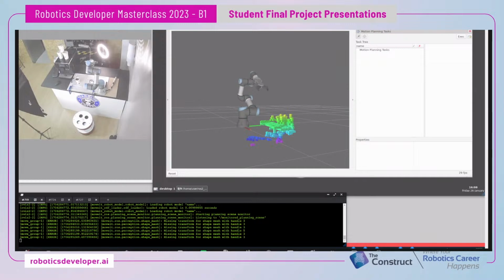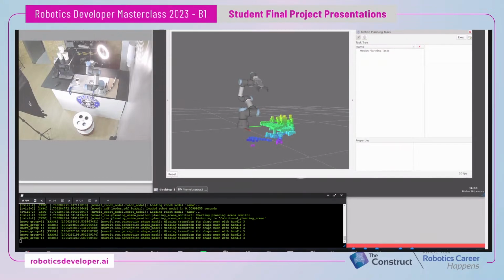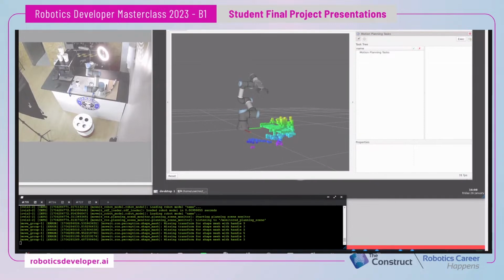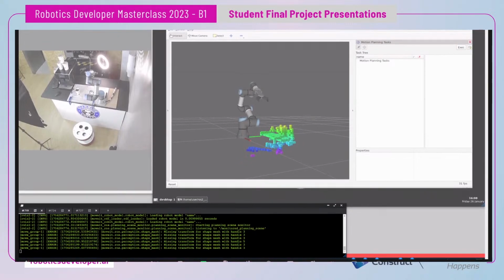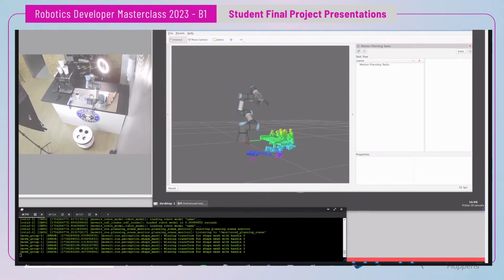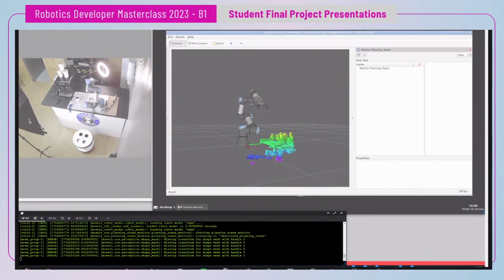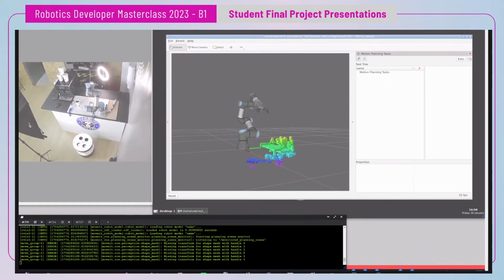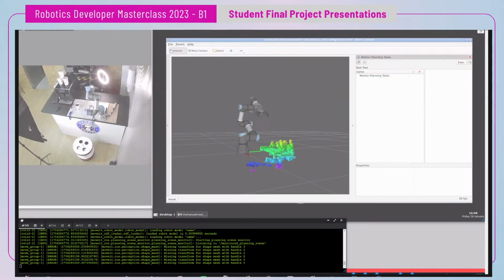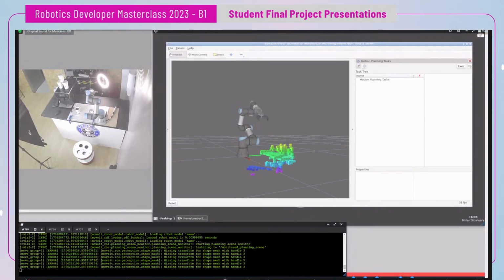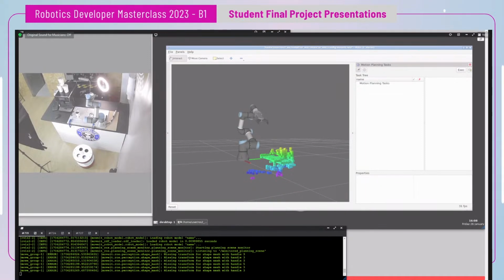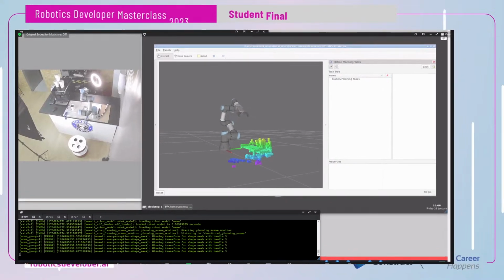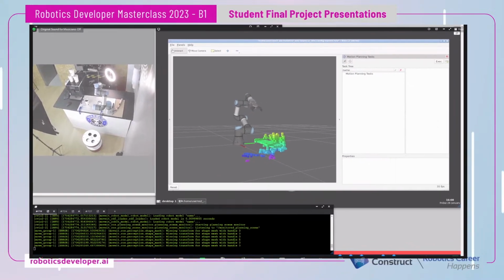They solve all of the stages individually, and then the task constructor framework tries to link those together into one full plan. So for example, it would solve the kinematics for the grasping position while simultaneously attempting to figure out the actual path from its current position to that grasping position, and then it would try and link that to the next position, say the fill position, and so on and so forth.